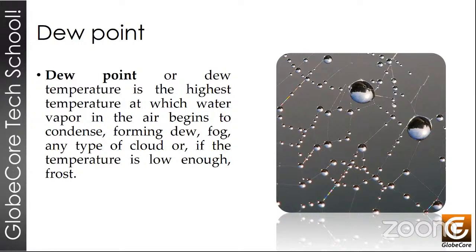The general procedure usually is to fill the transformer with dry gas, that would be air or nitrogen, in such a way that after a certain time, during which a state of equilibrium in humidity is achieved, the dew point of gas is then measured, and that value allows us to determine the residual moisture in the solid insulation. Next slide, please.